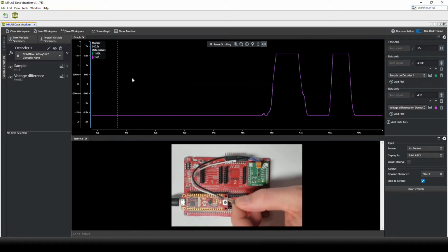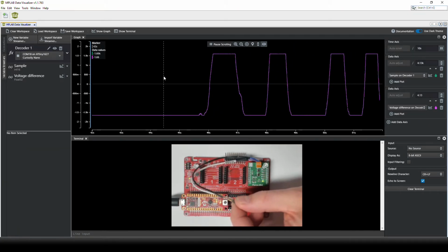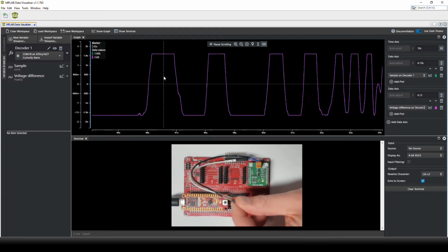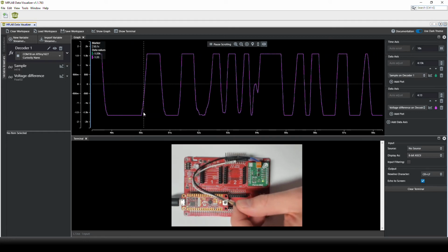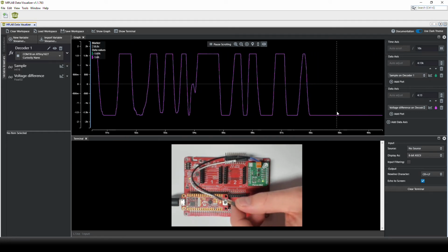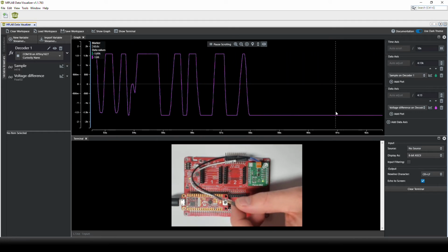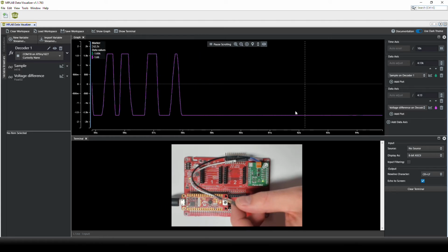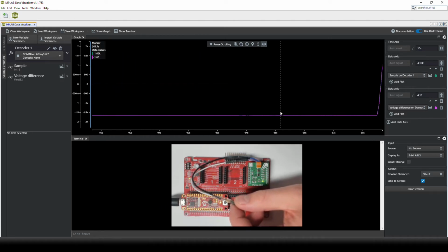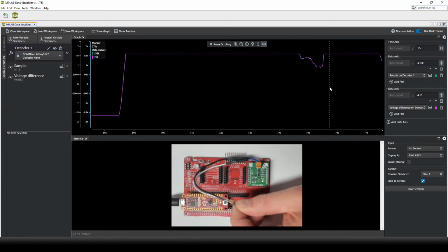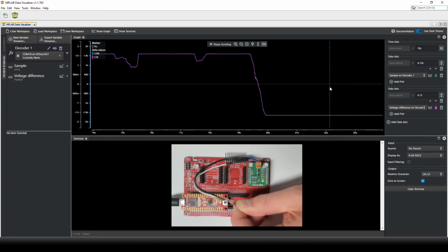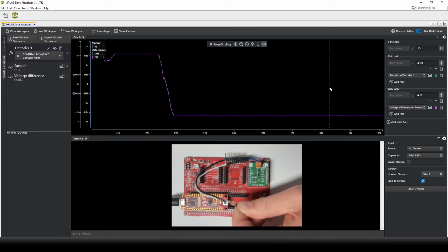And if I press the button to get autoscale to work, we can now see that the signal varies from down at the bottom, almost minus 1.65, which is as expected. And the top is almost reaching 1.65, which is also as expected, as 3.3 minus 1.65 is 1.65, and 0 minus 1.65 is minus 1.65.